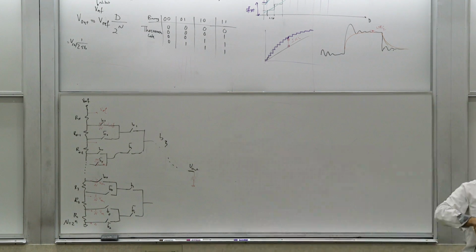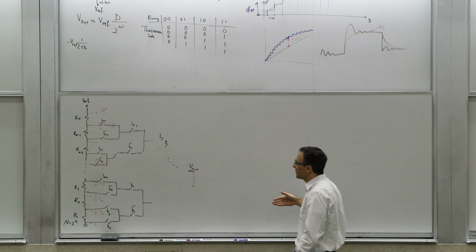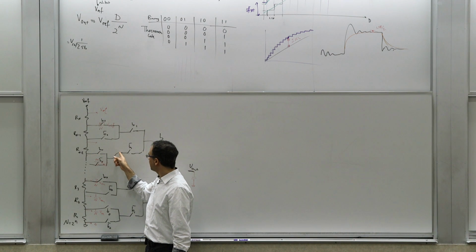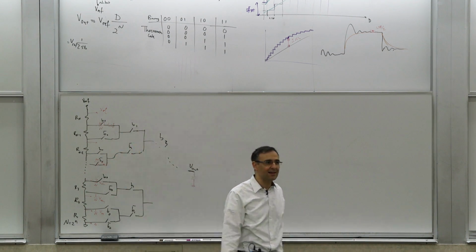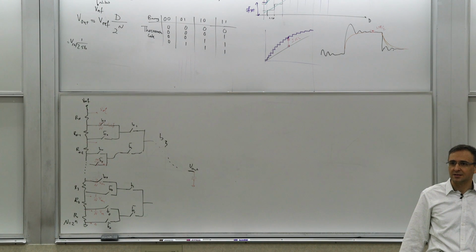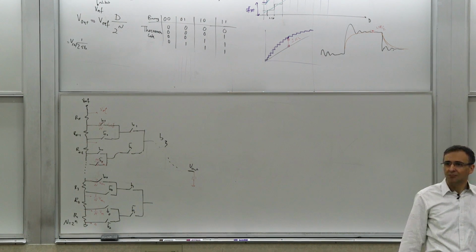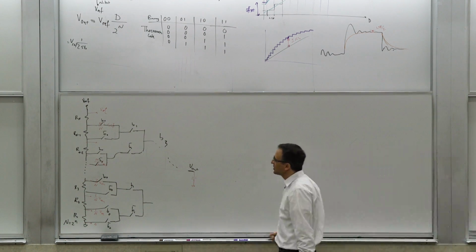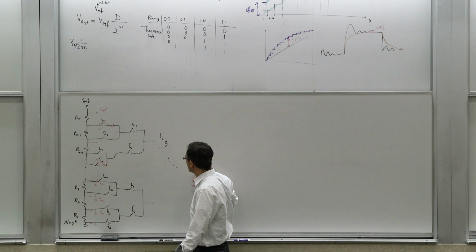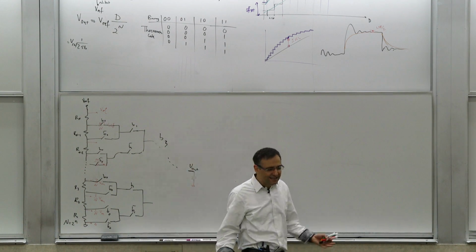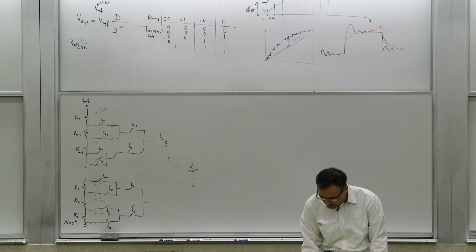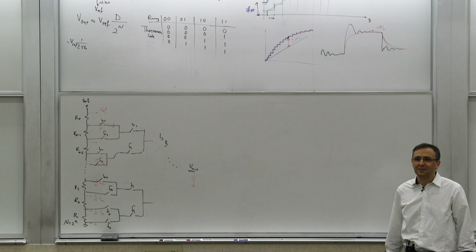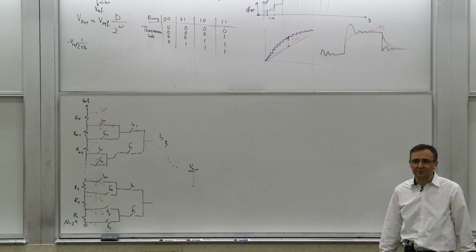The other thing is that even if it were not dependent on that, if you're somewhere in the middle, you have a bunch of resistors. You have a large time constant, plus all the series resistance of the switches. You have n, lowercase n, switches in series, right, where you're connecting. So you have a fair amount of resistance. You're charging and discharging this capacitor through this large resistor. So yeah, if you were really trying to make a quick and dirty D2A, yes, this does work. So you know, at least one D2A, but it's not the best D2A.